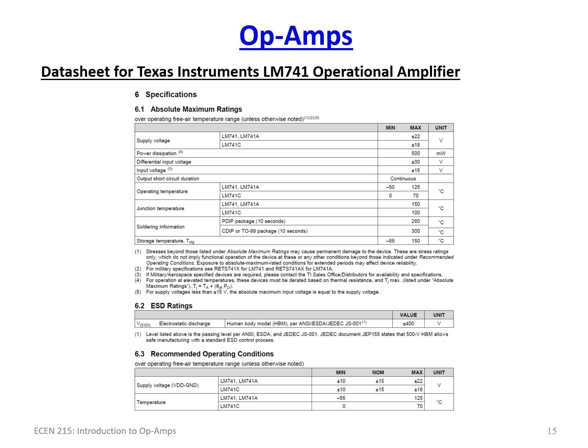So it is very important to pay attention to these. And of course, the input voltage is limited to plus 15 or minus 15. So that's where you can get the plus or minus 30, but you cannot put anything more than 15 volts on a particular input pin. So again, when you're working with real devices, you really got to pay attention to these absolute maximum ratings. If you violate these ratings, the chip will actually smoke on you.